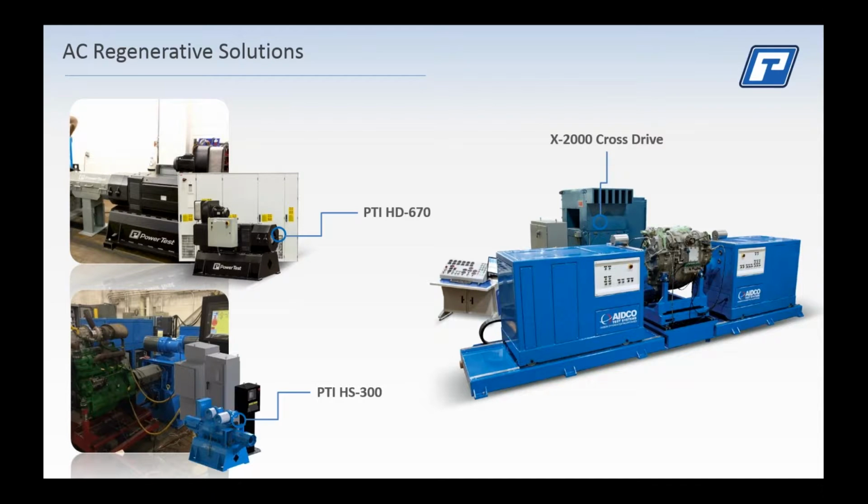Getting into power test engineered solutions, AC Regenerative Technology has been prevalent for several decades now. It's got better and better as it goes, and the costs have decreased accordingly. The way that an AC regenerative system is used is it is using AC induction motors typically as either the motoring supply to drive or the absorbing load to load the output.